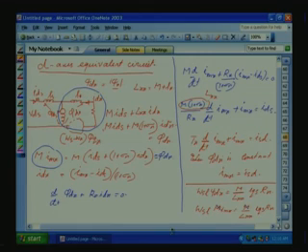So, what is omega slip? The final equation is omega slip is equal to IQS divided by, see, RR by LRR, that is 1 by TR, rotor time constant, into IMR. IMR is equal to IDS when the flux is kept constant. So, omega slip is proportional to IQS. So, we got the correct conditions for field oriented control.